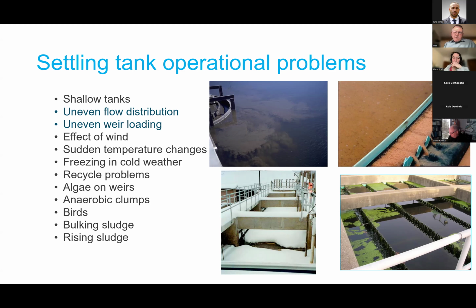And then rising sludge, when you have denitrification in the clarifier, and the nitrogen bubbles float the flocs up. That is something that we either take into account in an empirical way in the flocculant part of the settling equations, or I've seen it also linked directly to the amount of denitrification. So the denitrification rate can influence the flocculant settling parameter.